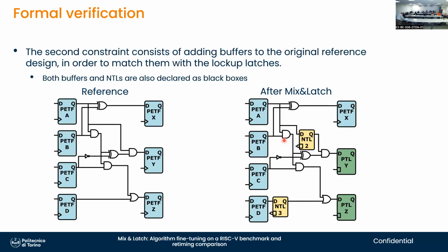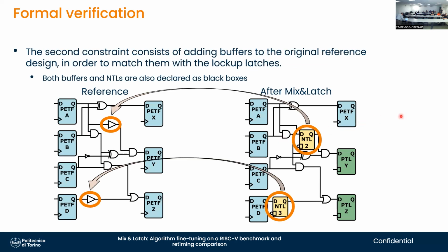And while doing so, please make sure that you treat these negative latches as buffers. So we insert some other gates that are considered as black boxes in here, and we declare them as transparent black boxes. So at this point, we check the combinational logic before and after the black boxes, and if everything is equal, equivalence checking is passed. Timing analysis will tell us if signals arrive on time. That's the first thing.